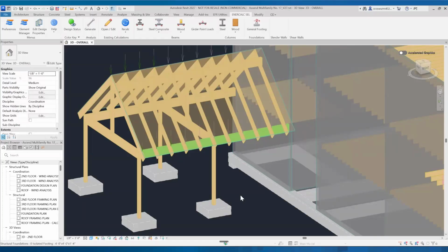So in contrast to a beam, where we're usually looking at span geometry, how far between supports, what our fixity conditions are, and so on, when we do this for columns we're mainly talking about things like our slenderness profile, right? What are your brace point locations? What is your unbraced length? What are your effective length K factors, and so on.